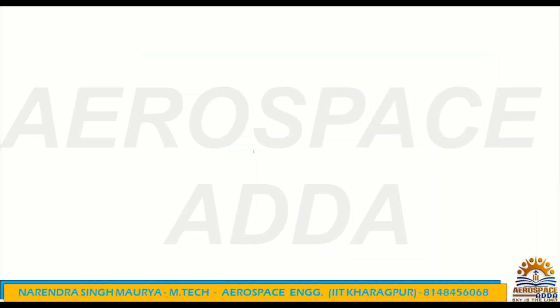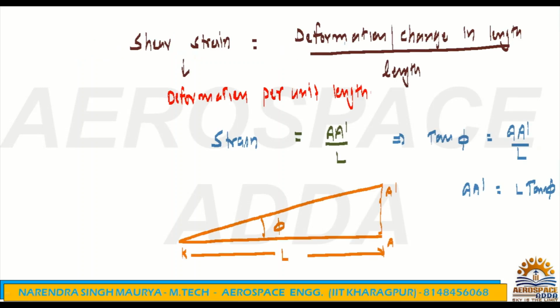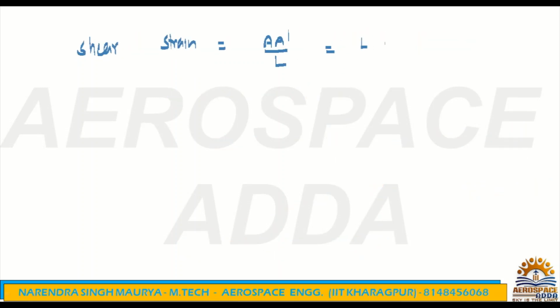If I write the strain formula again, what is strain? Shear strain, because we have a twisting moment. Shear strain is AA dash by L. Just now you got AA dash, it's L tan phi. So L tan phi divided by L, cancel out. What will you have? Tan phi. What will be the shear strain? It's nothing but tan phi.